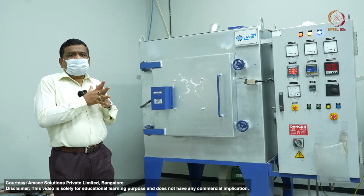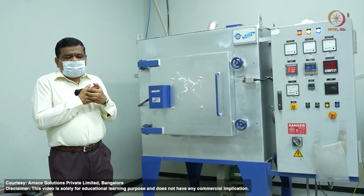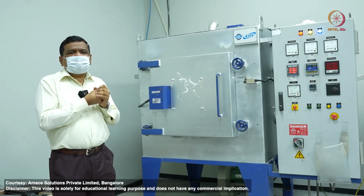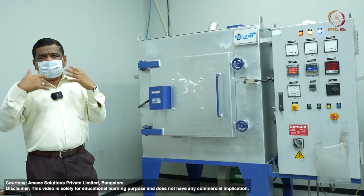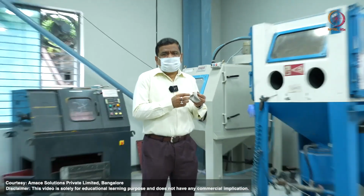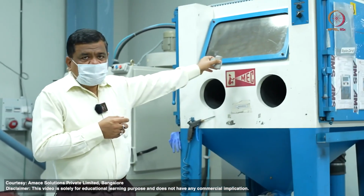The purpose of the heat treatment is to relieve the residual stresses which are generated during the laser powder-based fusion processes. As I have mentioned, during the interaction of the very intense laser beam with the metal powders, a significant amount of residual stress is generated during the processing itself. The purpose of heat treatment is to relieve this residual stress before the parts go for further grit blasting. After the heat treatment, the support structures are removed from the additively manufactured implants, and you can see the support structure is removed, and then this goes to the grit blasting.